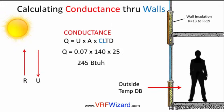So, calculating conductance through walls. It's basically the same as the conductance through the window, but we're not going to get into what the TD, temperature difference, and CL are. CL just takes into consideration the thermal capacity of the building to hold heat and then release it later on. But working with this delta T just gives you a good idea of how the equation works and how to figure your CFM.